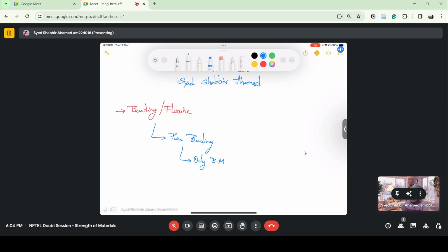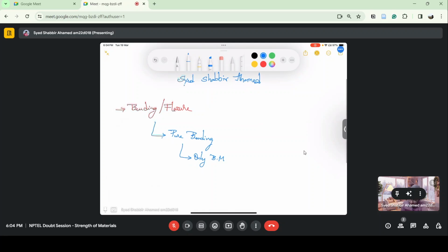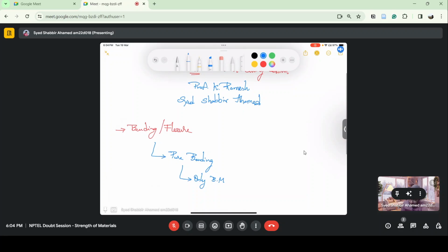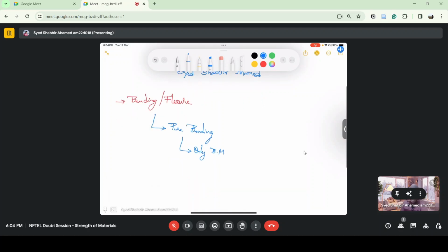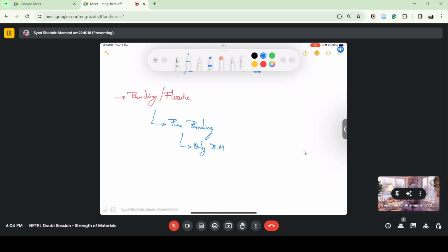Because we are mainly dealing with linear problems, we can get bending stresses, shear stresses, and axial stresses, and sum them using the principle of superposition, because as long as the problem is linear, we can use superposition to get the whole effect.